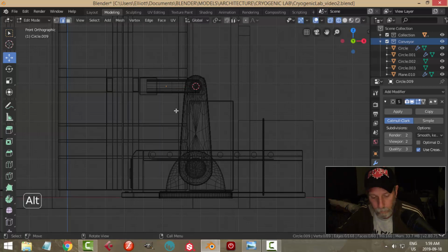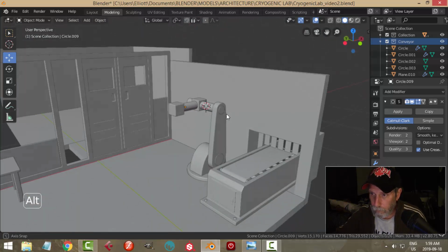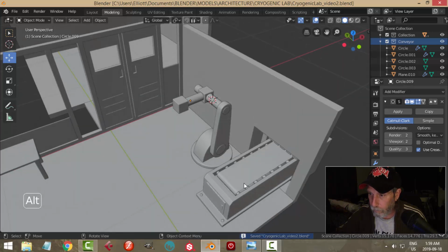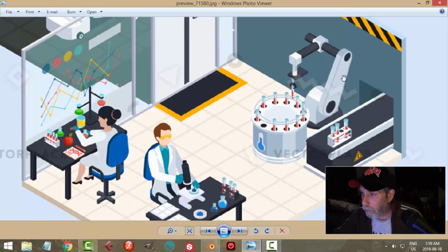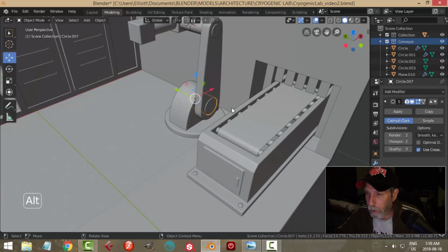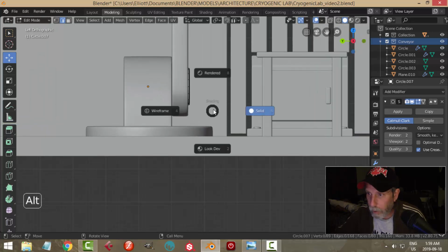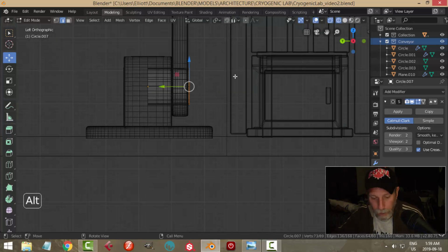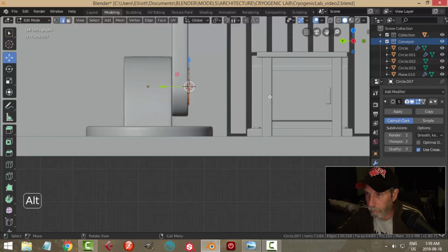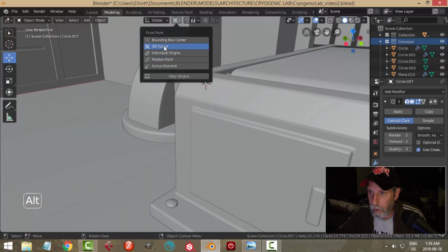Delete those. Now, before I go much further, I better angle that back. The way I think I'll do that is I'm going to select, I think in wireframe, box select all that and Shift S. Cursor to select it there. And I'll switch to 3D cursor.